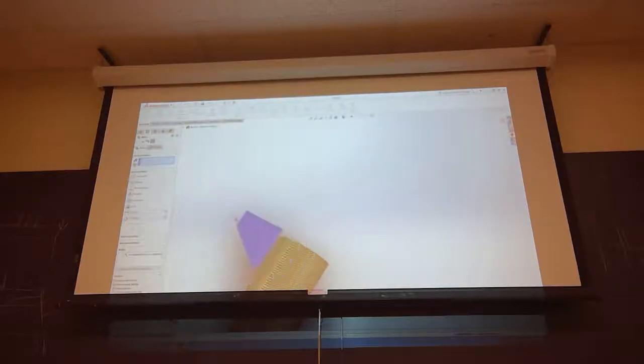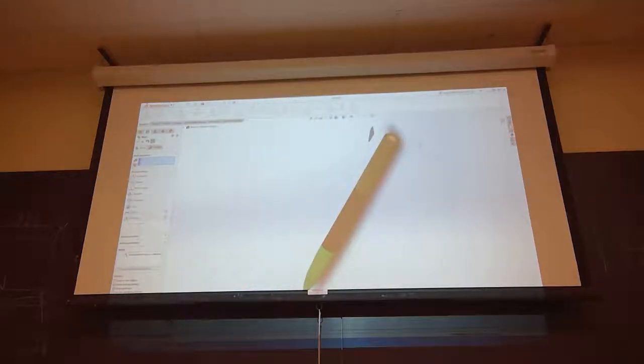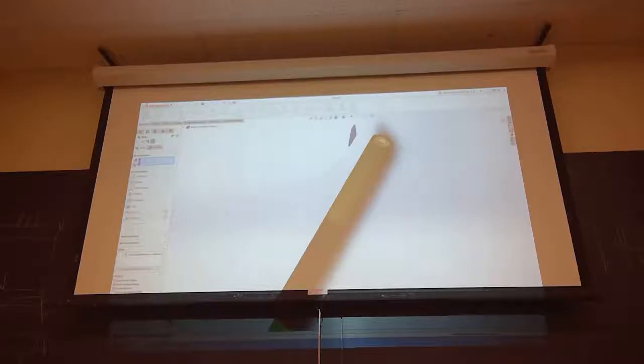Yeah, just change the face. Okay, so you should look something like this. What are we making coincident? You're making the bottom part of the fin coincident with the bottom part of your tubing. Okay, and you might run into the problem where it's flipped. So just make sure that when you finish the mate, the top is pointed in the correct direction relative to the tubing.